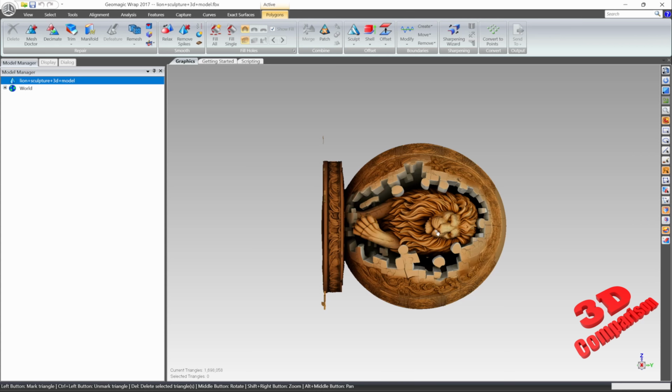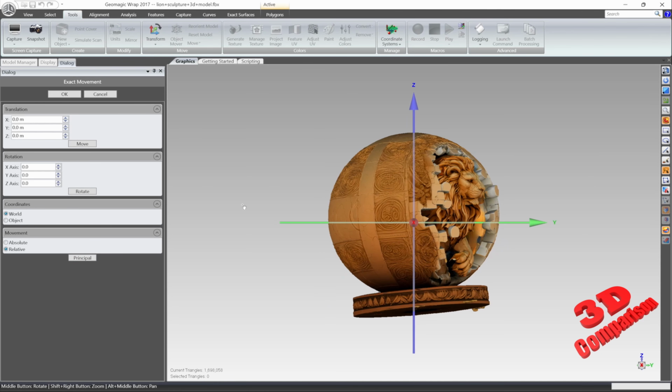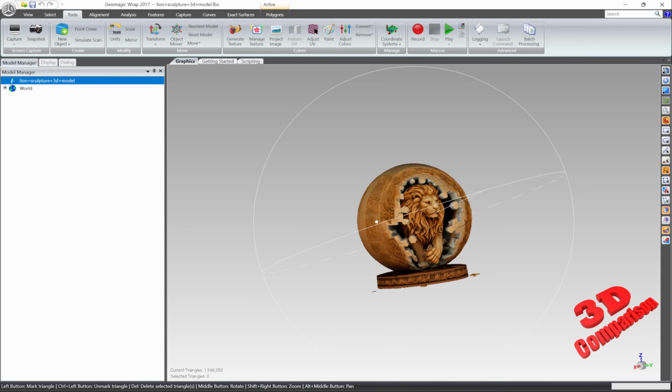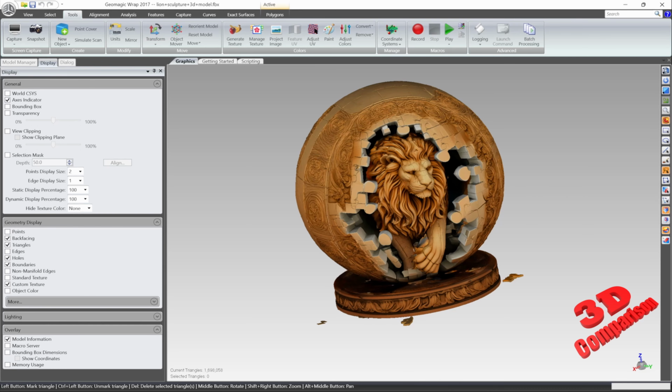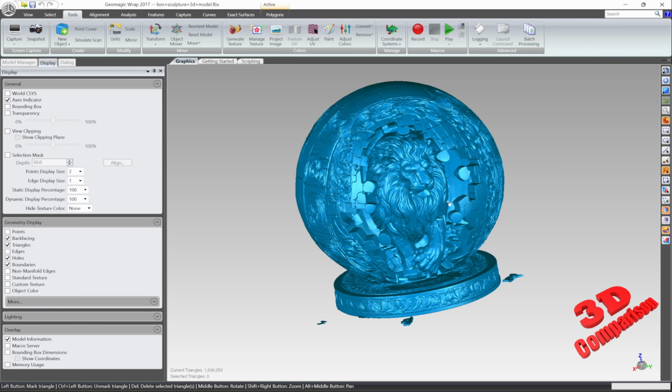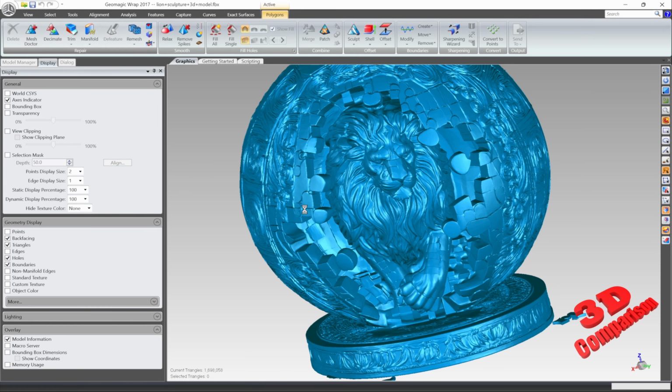We see that for the orientation, GeoMagick will have the z-axis going upwards. So I'm just going to slightly position this in order to have it align within GeoMagick. So this will be a better alignment. I will disable the texture since that is not the most important thing over here. And I want to analyze the total amount of elements within the mesh. So I'm going to go over here within polygons, mesh doctor, and let's analyze the mesh created by Tripo.